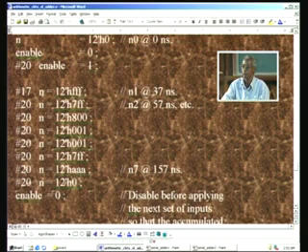N1 is minus 1, notice this one, this is in 2's complement, and all these things are in different values. The last value is just a dummy thing, because the last n7 value is this one, the n0 value is this one, and every 20 nanosecond we apply, and the data we offset as we have done before, so that data is always ready when the clock strikes.